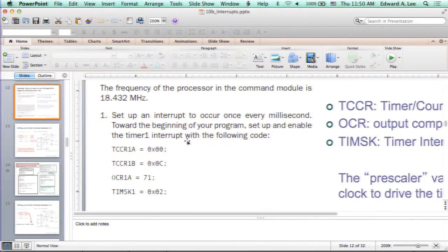Normally, an interrupt is handled between instructions. But the ARM processor has an instruction that can take an arbitrarily long amount of time to execute. So if you want to handle your interrupt with precise timing, you better not use that bulk transfer instruction, because if you do, you're going to get your interrupts delayed by an unknown amount of time if you happen to get the interrupt during that bulk transfer.